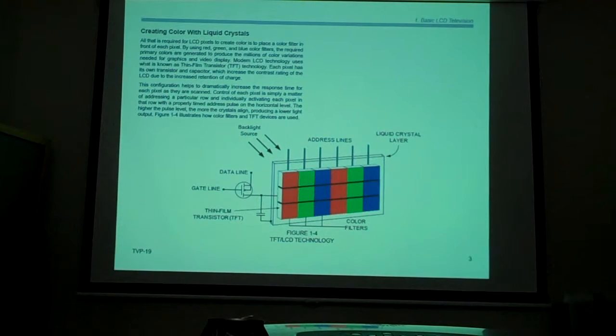And so, for example, I'll be passing around in a minute a sample LCD panel, and these filters run from top to bottom. So there'll be a red stripe all the way from the top to the bottom, a blue stripe, a green stripe, and they just keep repeating like that. The LCD material itself can pass light from infrared up through the lower end of UV.